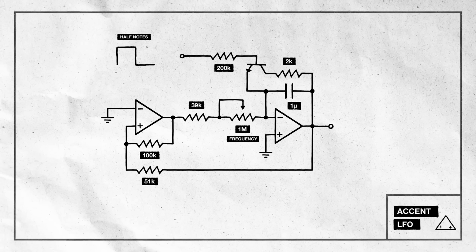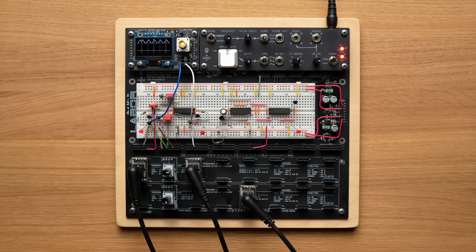So before we can use it, we'll need to shape the chip's output into a short voltage spike by adding a small cap at the oscillator's reset input. The cap only lets a quick burst of current through, creating the short pulse we need. Okay, that was a long preamble. Let's see if this actually works as intended.